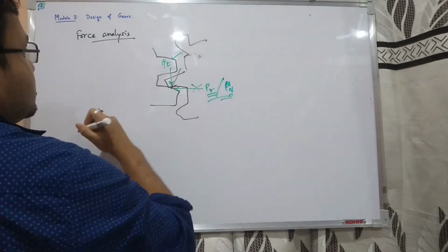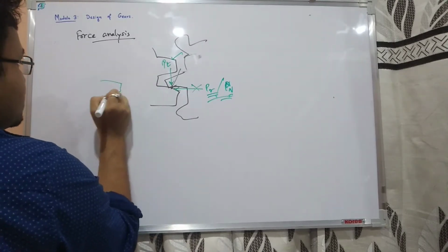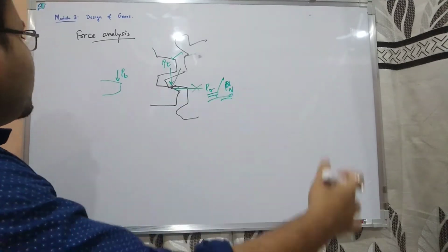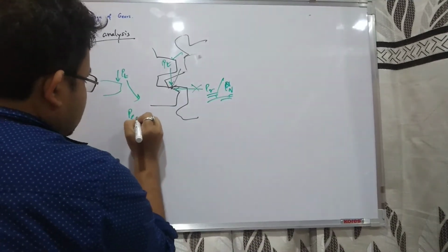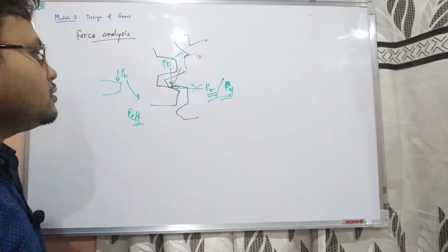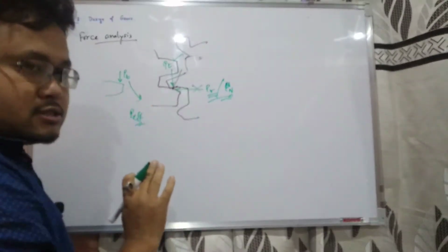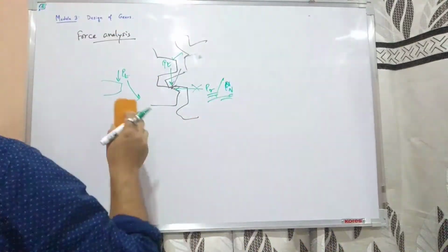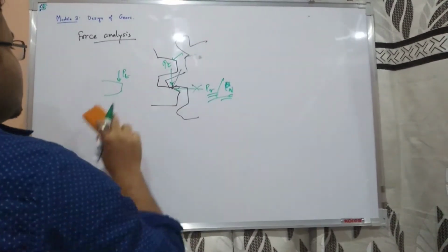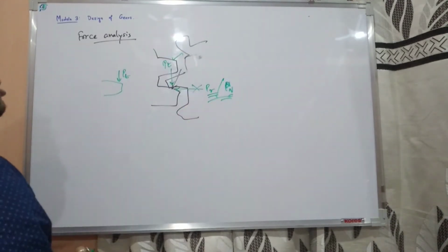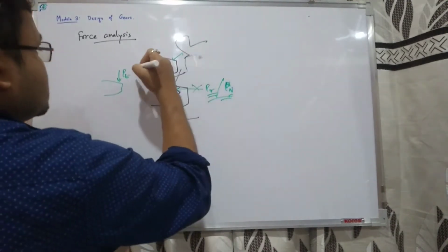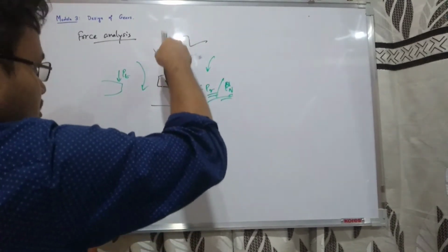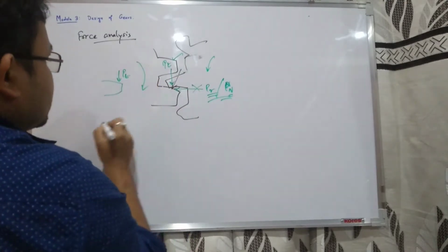So we take that load as the static load in this case, PT, and later we modify this to a new load that is called P effective. We'll talk about that thing. By considering the effect of variations, we modify this PT to P effective. That I'll tell you later. For the time being, we take this PT as the force which is causing the gears to rotate. I mean, this gear is pushing this gear with the force of PT, and this is rotating in this manner.